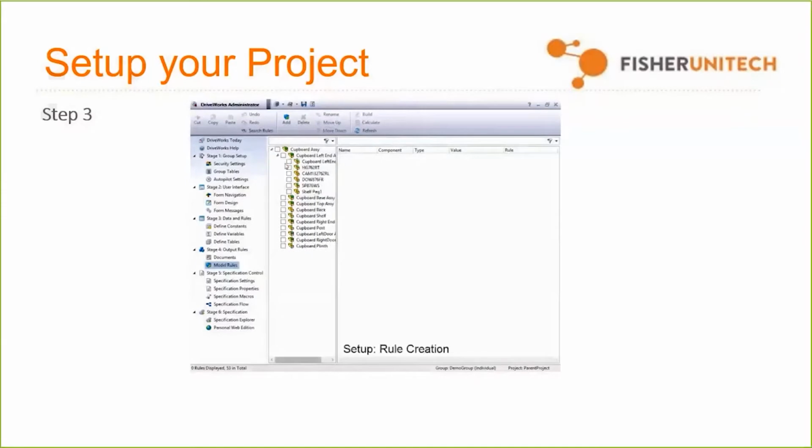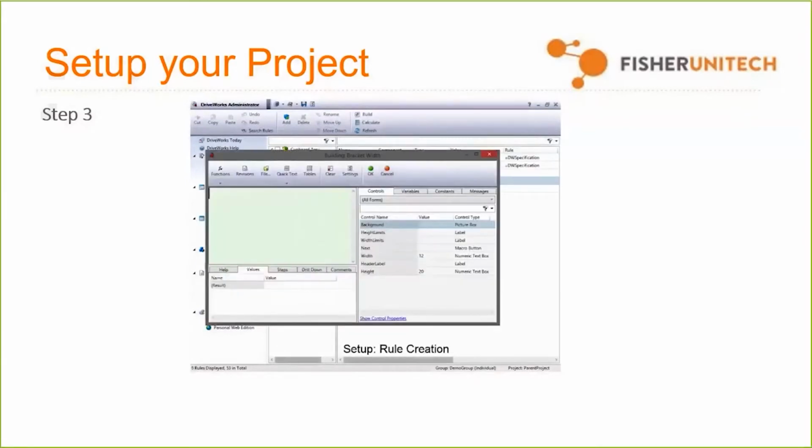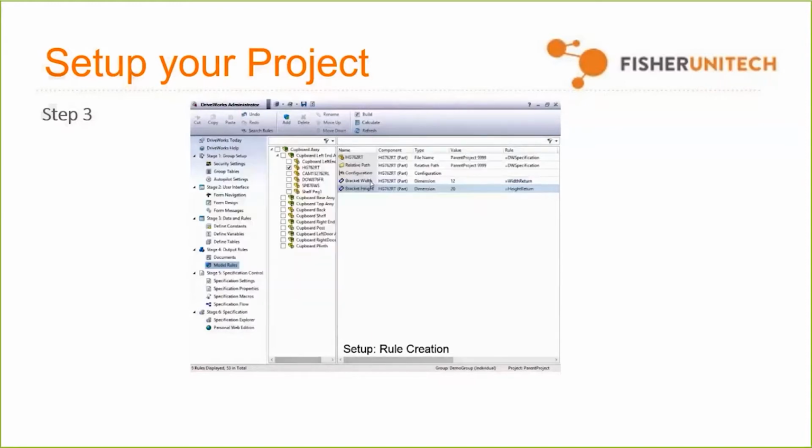So I'll go ahead and play here, and you can see that now we take the same bracket and we're going to attach it to the exact same form controls you just created with a little syntax by double-clicking, and then using the height return and the width return. The syntax return at the end just means it came from a form control. And that little dialog that you saw was just a place where we can click on the very form controls we just created when we were doing that form.